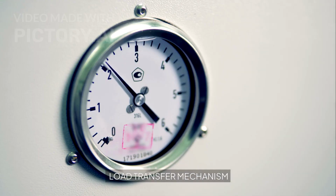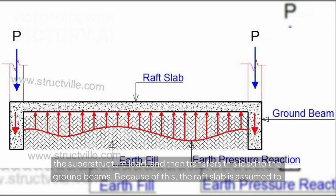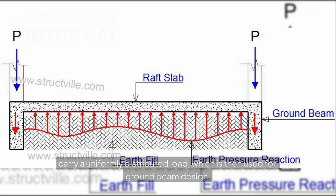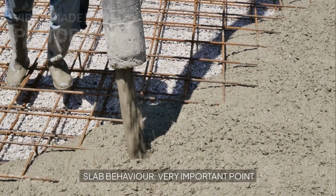Load transfer mechanism. In beam and raft foundations, the design assumption is that the raft slab first resists the earth pressure generated by the superstructure load, and then transfers this load to the ground beams. Because of this, the raft slab is assumed to carry a uniformly distributed load, which is then used for ground beam design.